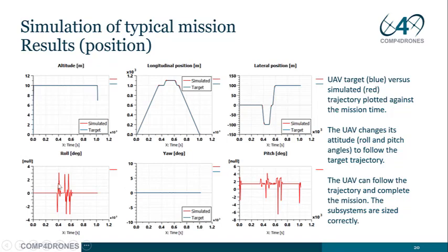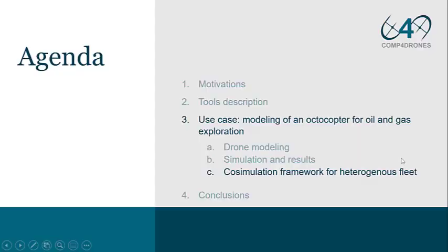So as I said before, the roll and pitch vary during the mission so that the longitudinal and lateral positions are followed. And you can see that we also imposed the yaw angle to be 0 throughout the whole mission. So the conclusion from these results is that the UAV can follow the trajectory and complete the mission, so the subsystems are sized correctly. The final part of the use case consisted in the creation of a co-simulation framework for